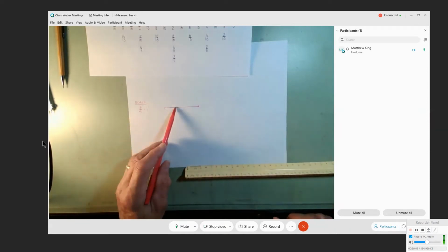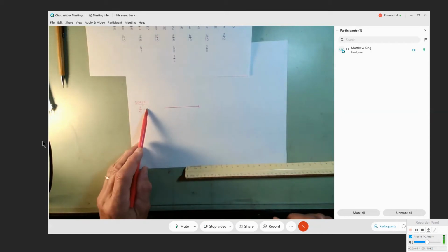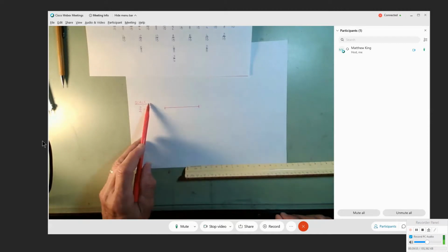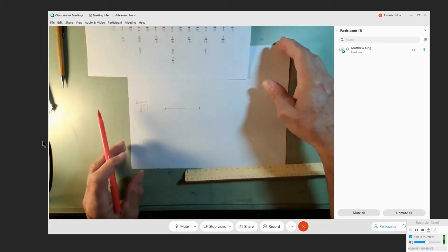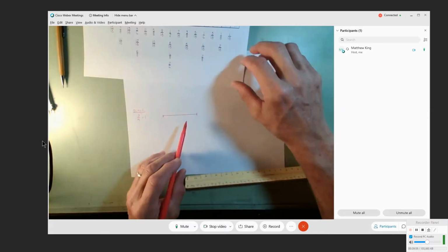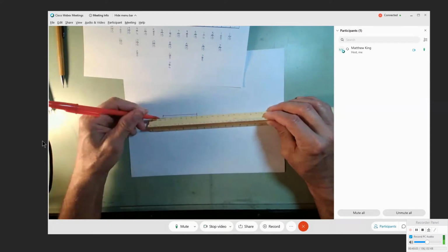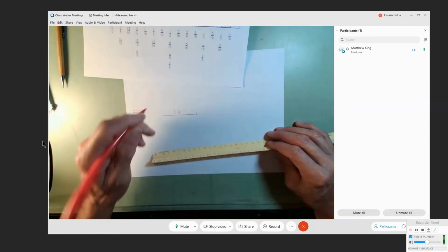The scale for this line on that drawing you would write as 3/4 inch equals an inch. Another way of saying that, for every 3/4 inches on my line work, it represents 1 inch in the real world. Now, I would say that this line measures, right, we measured it, it's 3 1/4 inches in length.